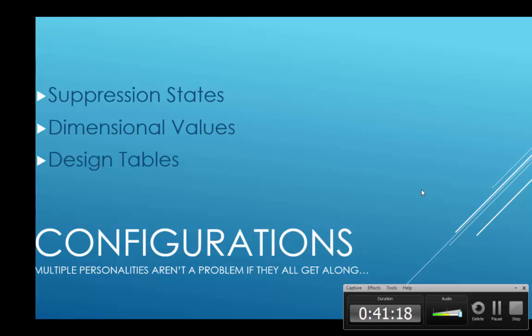I have seen people actually create a design table from scratch. They're like, oh, it's D3, a sketch 4, and I'm like, what are you even doing? That's just crazy. So if you leave it as it is, like I had naturally in there, it is stored within the part file. And there have been times where you'll try to edit the Excel file itself, and it'll pop up and say, sorry, file's been corrupt. There's not much we can do on those.